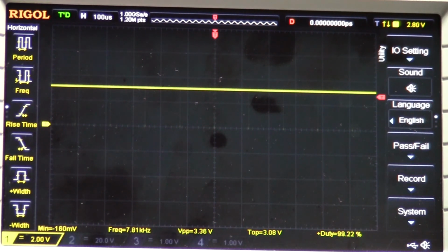So now let's say we want 50%. For 50%, we know that we need to set a value of 512 decimal, which would equate to basically a hexadecimal number of 800. So that will set the 10th bit, or bit 9 if you will, of the pulse width modulation duty cycle select.